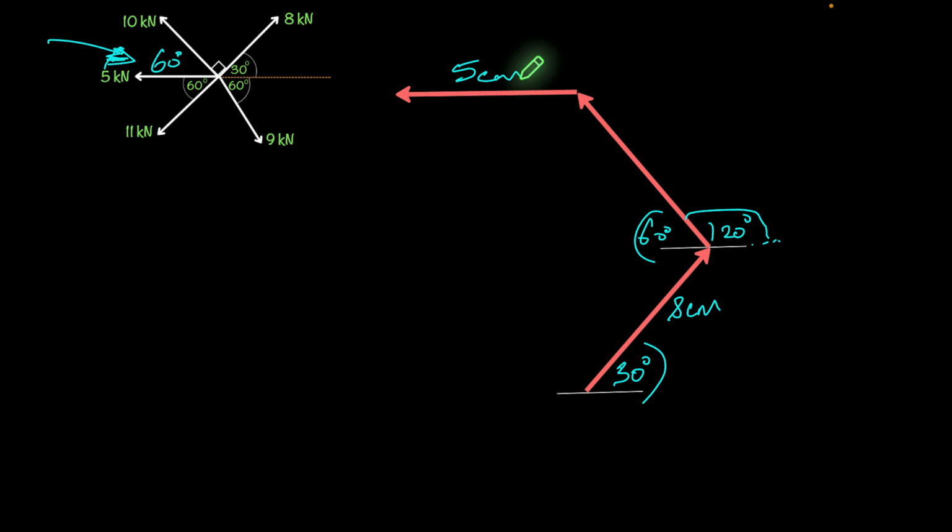So that's going to be that horizontal force right here that we have, which is 5 kilonewtons. And of course, the previous one that we drew in was just 10 centimeters because that measured 10 kilonewtons. Now, because this 5 kilonewtons is a horizontal line, this can just serve as the reference line for our next angle.